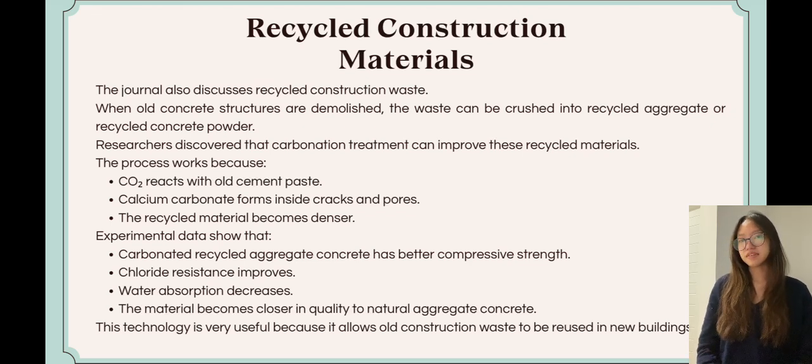Recycled construction materials. The journal also discussed recycled construction waste. When old concrete structures are demolished, the waste can be crushed into recycled aggregate or recycled concrete powder. Researchers discovered that carbonation treatment can improve these recycled materials. The process works because carbon dioxide reacts with old cement paste. Calcium carbonate forms inside cracks and pores, and the recycled material becomes denser.